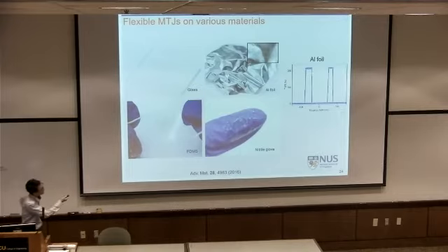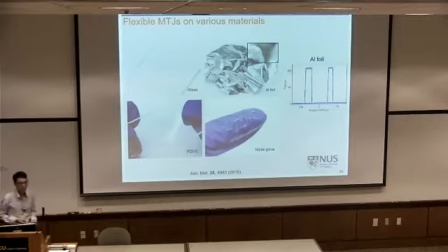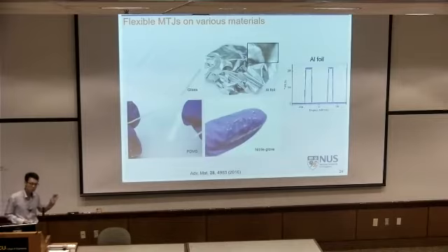And you can see the TMR response is more than 220% and a very square response and so on. So the junction property is maintained without any degradation. So I hope this gives some kind of proof of concept. Magnetic tunnel junctions or even MTJ-based sensors can be applicable to wearable or flexible electronics applications in the future.